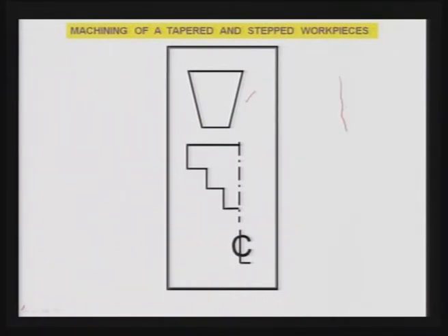Suppose you take a workpiece of this particular shape initially and you want to make this tapered workpiece. What you should do, you already have a control over there which will control the motion of this workpiece. Now you dip it in the etchant bath and slowly move the workpiece downward.